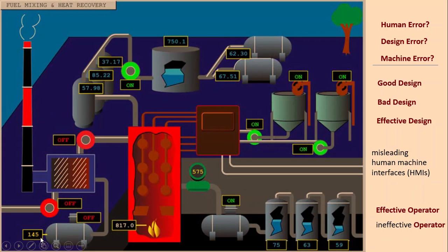tank. But if you notice carefully, all the numbers displaying here are without any measuring unit, or even the pump showing on and off status, but there is no additional information to it. So how to design a better version of it? Do you know the numbers showing here, is it pressure or temperature? Or if it is temperature, whether it is in Celsius or Fahrenheit?